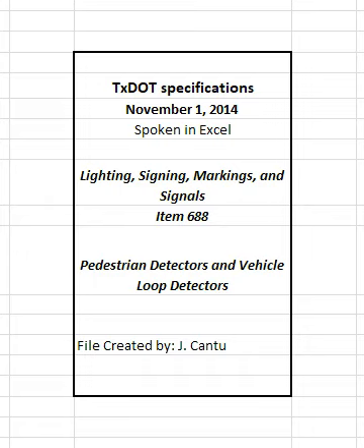Hold the loop wire in place every 2 feet with strips of rubber, neoprene flexible tubing, or polyethylene foam sealant approximately 1 inch long. Leave these strips in place and fill the slot with loop sealant.